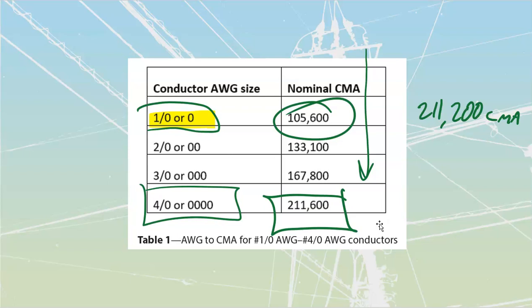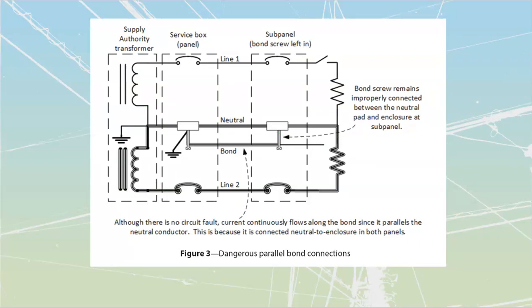All right. Terminating bonds. Terminating bonds is going to be less critical than terminating the actual ground. The ground used to have those restrictions that it had to be a permanent type of method, and then the bonds were allowed to be done with split bolts and everything like that. Now everything can be done with split bolts, but it does still need to stay in the path at all times. There are a bunch of rules that anytime I remove equipment, let's say I take a light off of an octagon box, the bonding path has to stay intact. That's why we have to mortise the bonds together in the back, and we take a whip off to our receptacles or to our lights or anything like that. So when we remove it, the bond path stays intact.